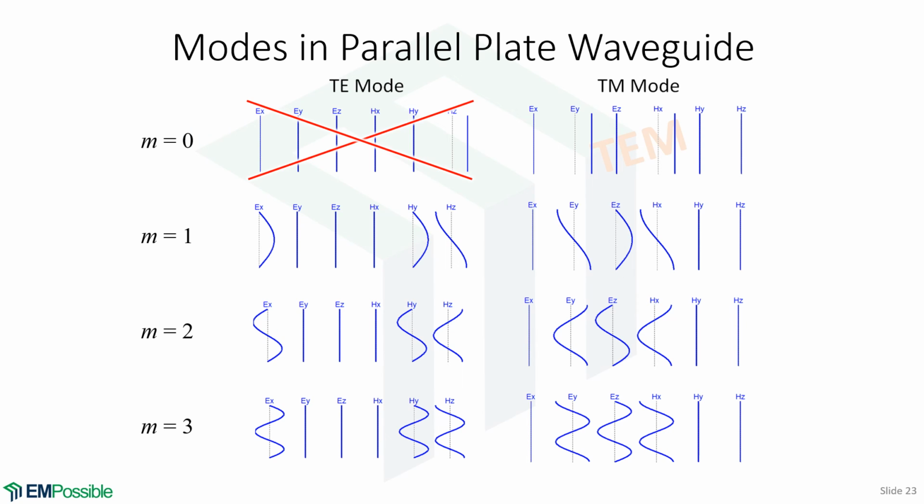I've plotted the first 3 order modes. We have equations for the TE0 mode. We know that it's not a physical mode. I went ahead and plotted them and X'd them out to remind us those don't actually exist. Our TM0 mode, notice everything is straight and uniform. That is clearly the TEM. And here's plots of the other modes. And it's a little bit more obvious here how we are looking at 2 half bright spots. So there's our modes.